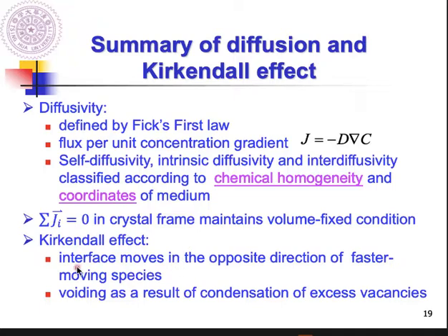There are two characteristics observed in the Kirkendall effect. The first one is that the interface is going to move toward the side with the faster moving species. And also the void will form in the material with the faster moving species, right? Okay, so that's the end of the first section.